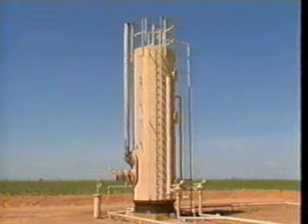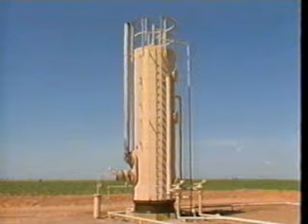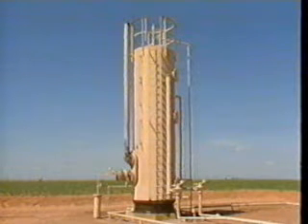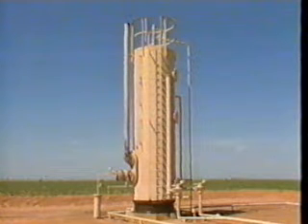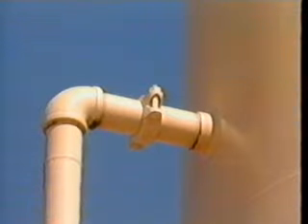In any case, we want the treating to be done at low cost, with the least addition of heat and the smallest decrease in oil gravity. The chemically treated emulsion enters the heater treater at the top, flows down to the bottom, and then back up through various treating sections. Each step brings the emulsion closer to complete separation of oil, gas, and water. Let's identify the external components of the heater treater.